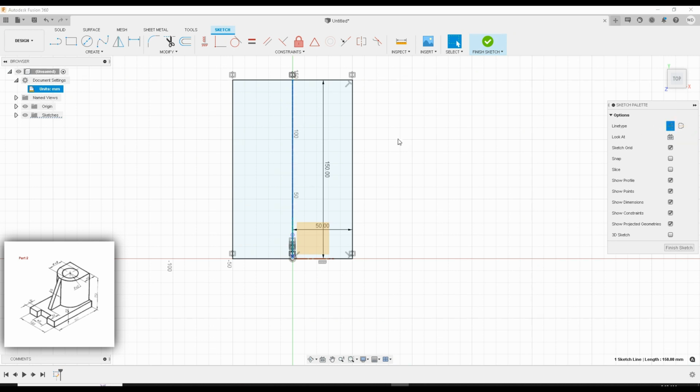All right, so let's see. We changed that to a construction line, so I selected that line. Actually, let's delete these. Okay, all right, so I deleted one of them because when I did the mirror, it duplicated the center line as well. So there were two center lines. It's a bit redundant. So let's select this line again. Go over to line type, and when you highlight, it's going to say construction. Go ahead, left click it. We turn it to a construction line.